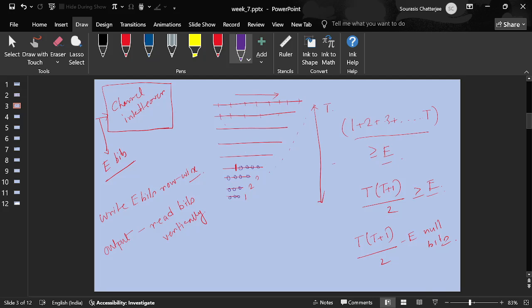So at the output we will again have E bits, and since we did segmentation and performed the rest of the operations in a blockwise manner, be it polar encoding, subblock interleaver, channel rate matching, channel interleaving, do I need to do something else, like concatenation of any kind, before mapping it to the grid? Is concatenation required or not?